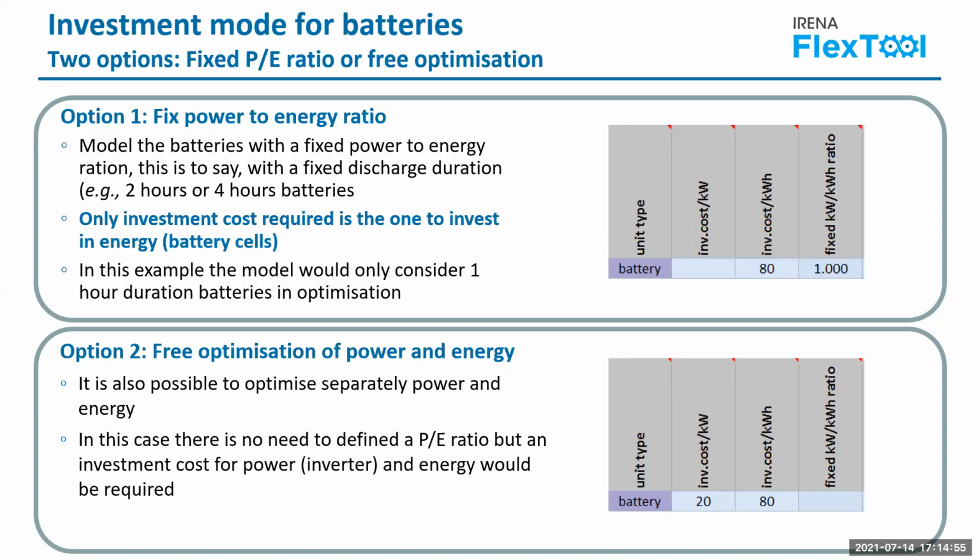So for instance, if we are talking about frequency regulation, that will likely require a higher power rating. While if we are talking about a system backup, going to adequacy, then we should probably favor better energy ratings. And typically batteries are designed to maximize performance in one or the other.